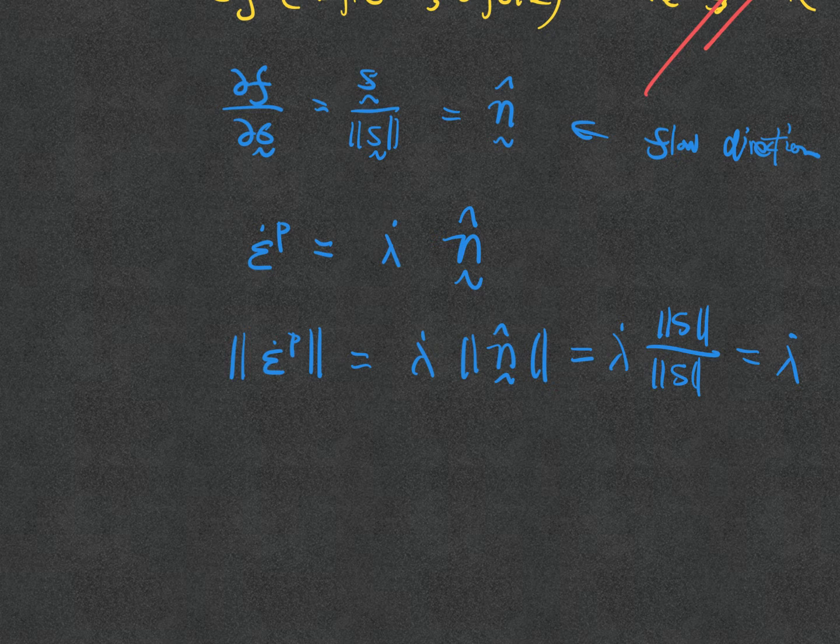Okay, so we have a separate way to mathematically represent how much plastic deformation I have in lambda dot, and the type of plastic deformation we have in the n vector. In this case, n is a tensor, but you can think about it in Voigt notation, where it becomes a vector. So the magnitude and the direction are represented separately, and when they combine, they give you the plastic strain direction. Okay, so then again, the case of epsilon dot p equal to 0 is for the